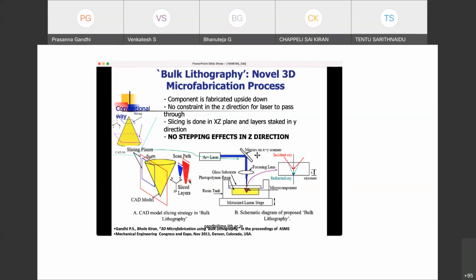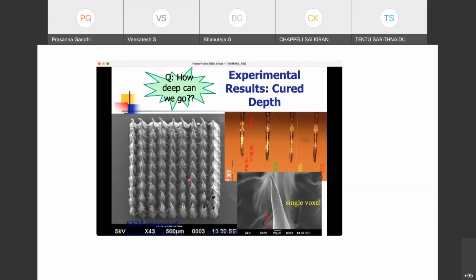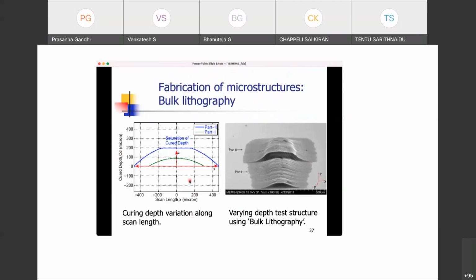Okay, that is the idea here, and that's what we have used to create components which are, say, simple needles like these, or very smoothly varying surfaces at a micron scale. If you see this, this is like a 100 micron dimension, and on that you get smooth variation from one end to the other. Otherwise this would have been just a four layer, 25 micron each, four step kind of material. Instead of that, we are now getting this smooth variation here. Okay,